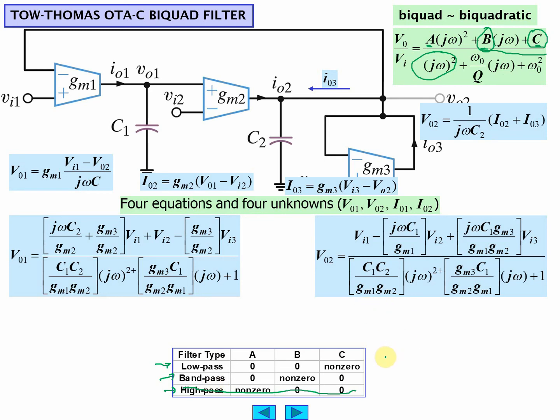What you're going to have is, remember the pole, it's going to be flat and then it's going to drop at the various frequencies. So at the high frequencies, the band pass, you're going to drop steep, 40 decibels per decade. And then over here on the other side, you're going to have a zero, which rises as frequency increases. It starts at a constant and then gets bigger. So it's never going to be absolutely 0 unless C equals 0.